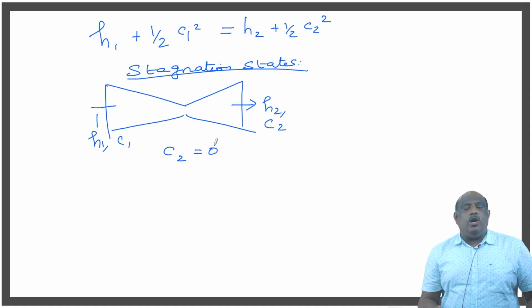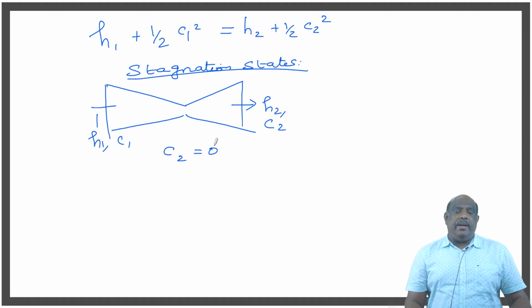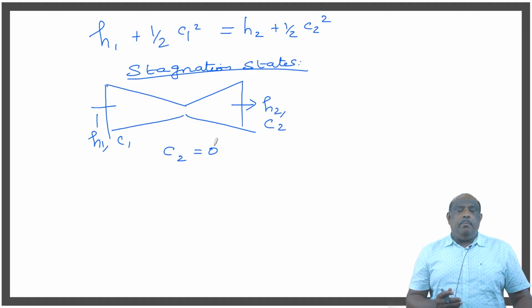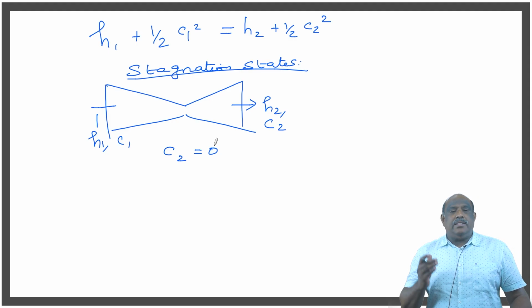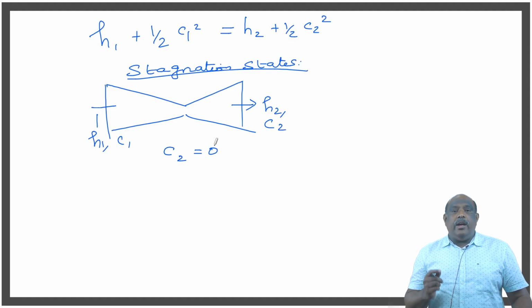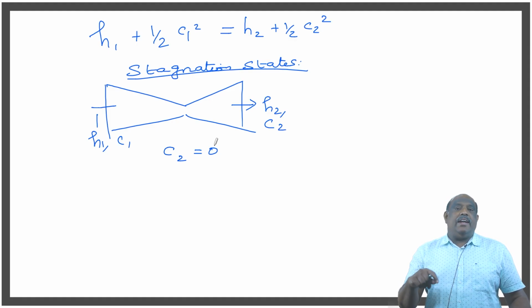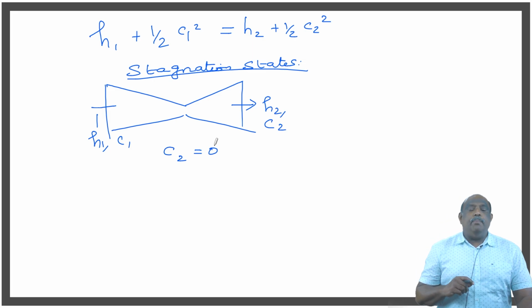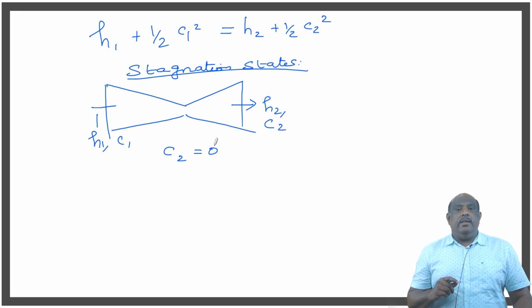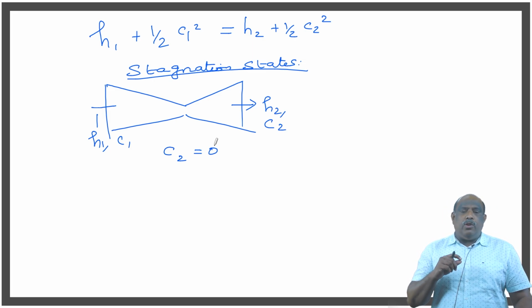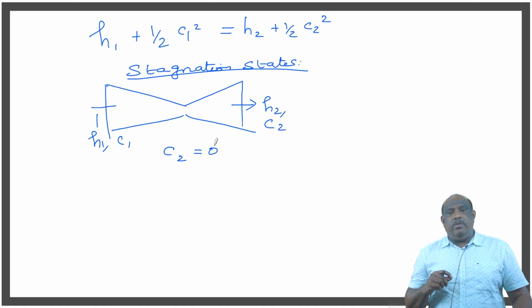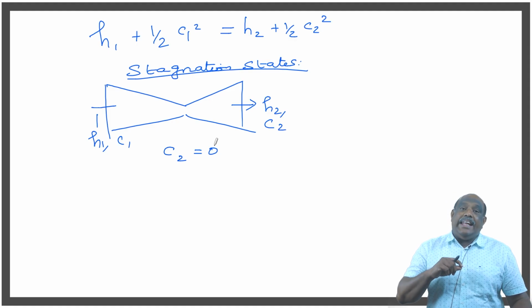0. It can be a nozzle, it can be a diffuser, it can be a heat exchanger, it can be a chimney. So it can be any open device. But finally, if I am going to make the flow stagnate after a particular condition, it is called what? Stagnation state. This stagnation state is possible when you adiabatically decelerate. Now the condition is imposed. What is the condition? That we are not simply going to make the flow become 0 velocity, but we are going to decelerate adiabatically.